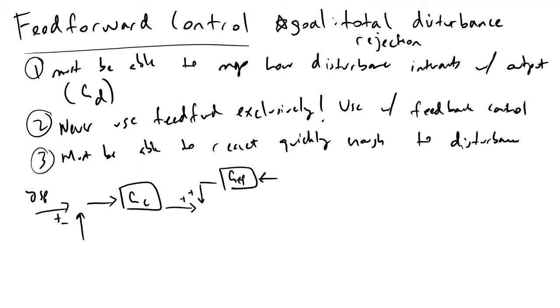And from the feed-forward controller, the input to that will be the transmitted disturbance. So if we had to measure the wind speed, this would be the airspeed meter, whatever you call it. And finally, we would have the disturbance itself, as well as the transfer function block GD, which is how the disturbance will interact with our system output. And we'll put that there.